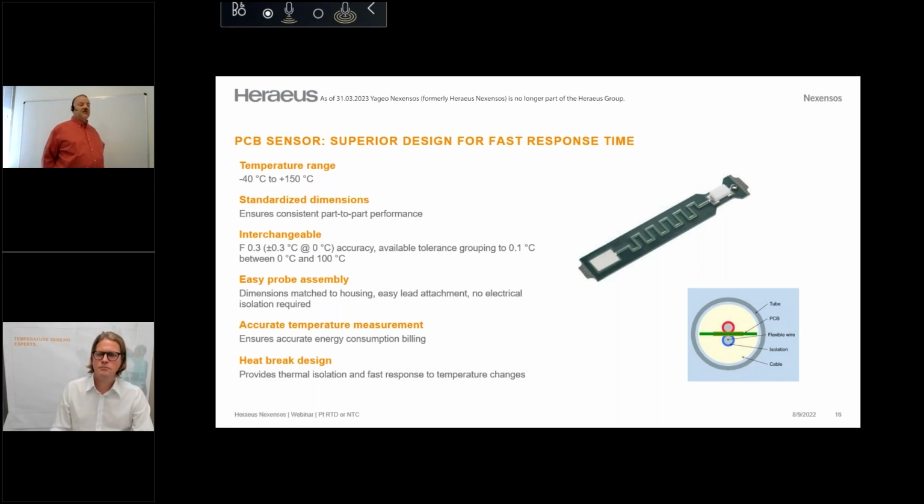And again, if you look at the green sensor itself, on the left-hand side of it, that's a solder pad, and there's solder pads on either side. So you slide a jacketed cable on that, and you solder the conductor to both sides, and you're done. And it saves an incredible amount of assembly time, and it can be very cost effective for HVAC and other applications over that temperature range.